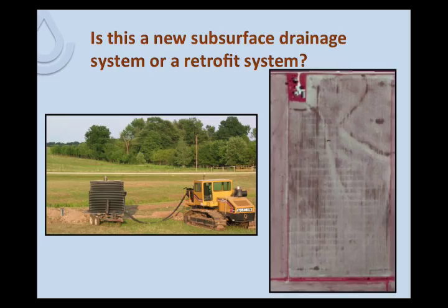There are several areas in the United States where new subsurface drainage systems are being designed, such as North and South Dakota, Missouri, and other states with extensive subsurface tile drainage. Drainage water management should be considered when planning new drainage systems or when a wetland determination is requested in order to improve subsurface drainage. A retrofit system should identify the location of mains and laterals. This will aid in the determination of the amount of area affected by drainage water management. A topographic map is also necessary to accurately place water level control structures and determine the land area that is affected by drainage water management.